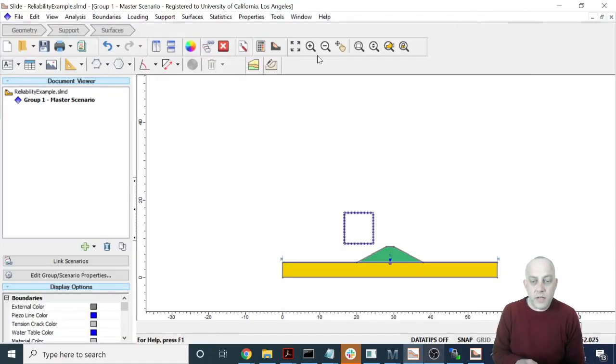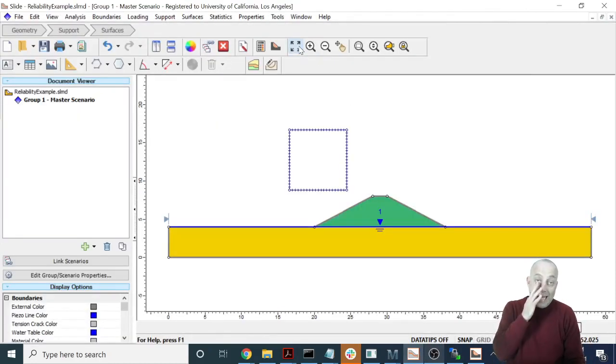All right, in this video, we're going to focus on analyzing embankments over soft compressible soil using a program like Slide to do our slope stability calculation. So I'm sketching that same kind of levee that we've been analyzing for all of the videos so far. And what I've done is put a piezo line here across the surface. So I'm assuming that the groundwater table was right at the surface before we constructed this levee.